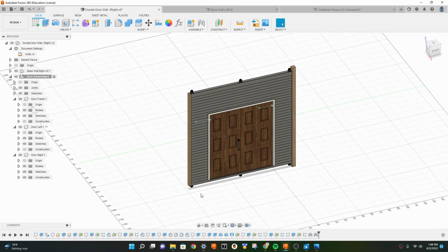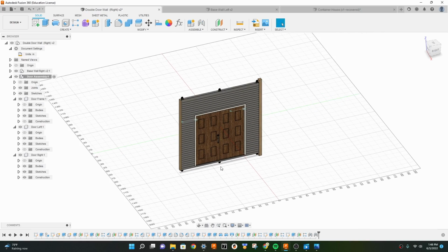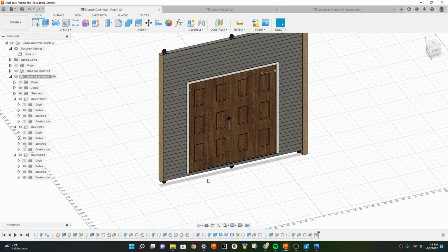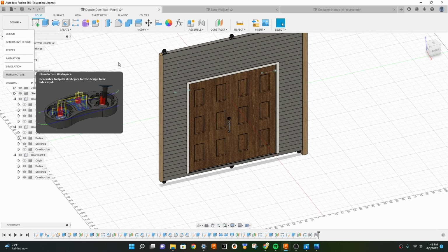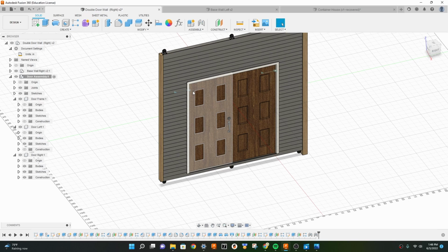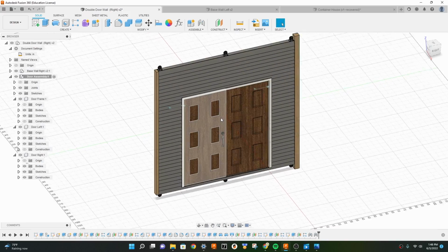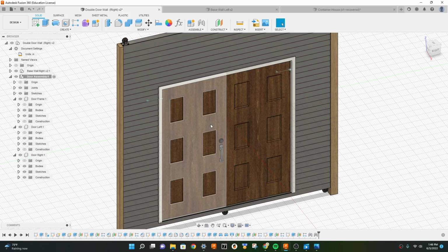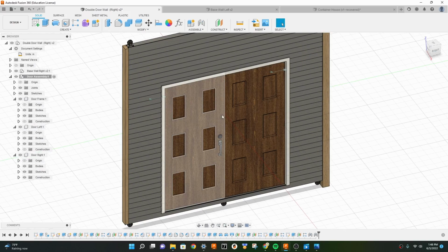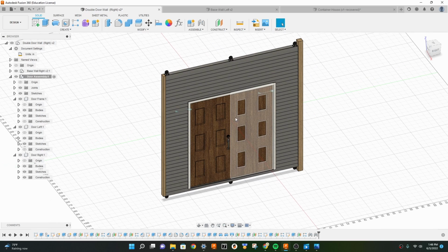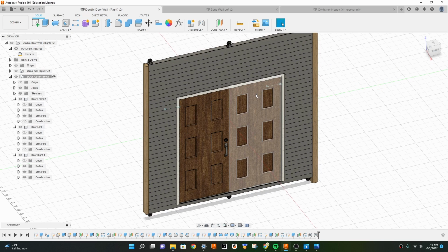So with this modular wall, I just want to talk about some key features about assemblies and components, so you can maybe create your assemblies and components a little easier. So essentially, if you want to maybe animate or create some renders here, you're gonna want some components and some joints. So to make joints, you're gonna need components, and what components are essentially, they can be bodies, but most of the time they're just, say, a specific part.